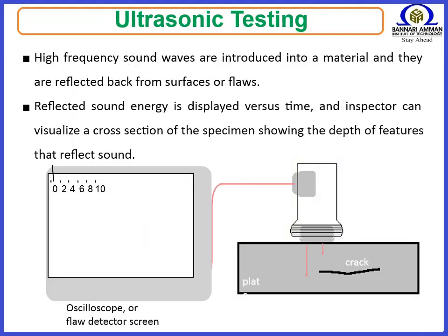Ultrasonic testing. Ultrasonic waves are introduced into a material where they travel in a straight line and at a constant speed. At surface interfaces some of the wave energy is reflected and some is transmitted. The amount of reflected or transmitted energy can be detected and provides information about the size of the reflector. The travel time of the sound can be measured and this provides information on the distance that the sound has traveled. Ultrasonic testing is a very versatile inspection method, and inspections can be accomplished in a number of different ways.